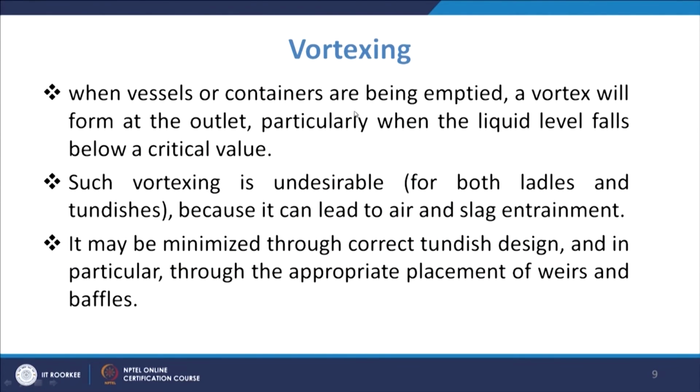In both cases, if vortexing occurs, it may lead to air as well as slag entrapment, because at the top you have the slag layer, and if there is vortexing, the air or the slag may be entrapped and go inside.